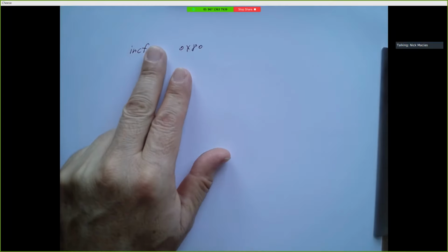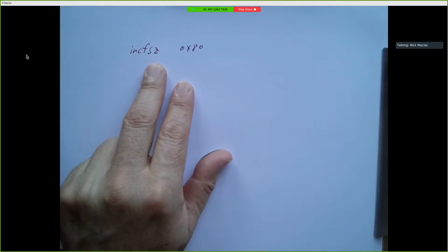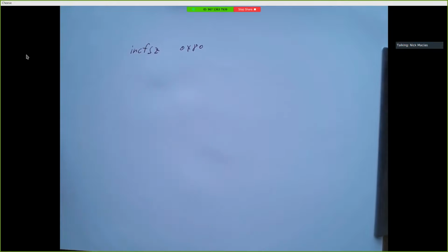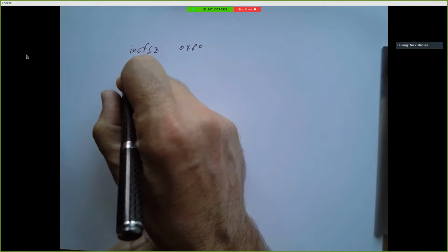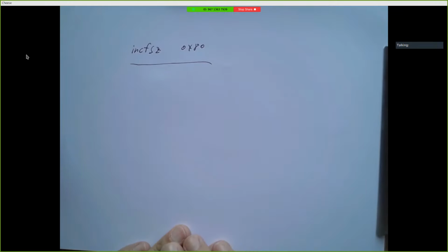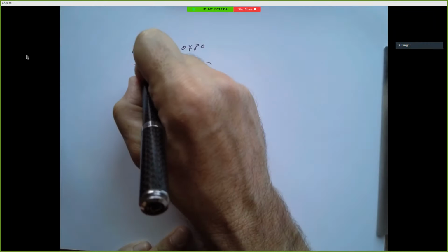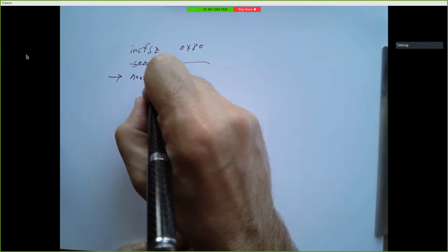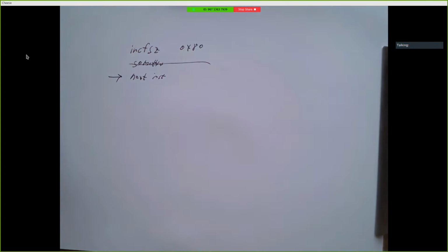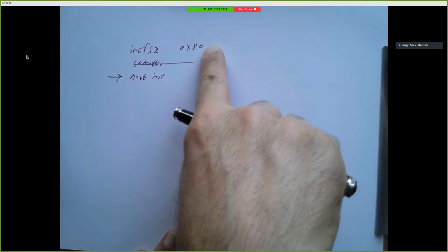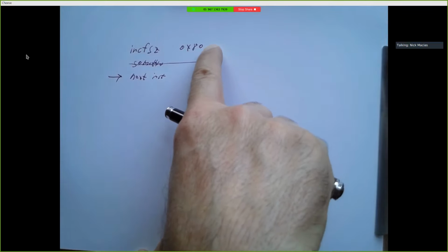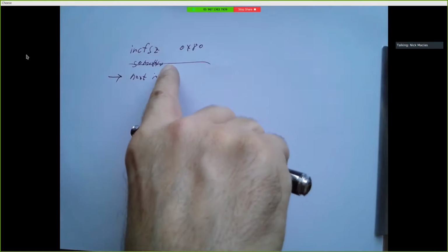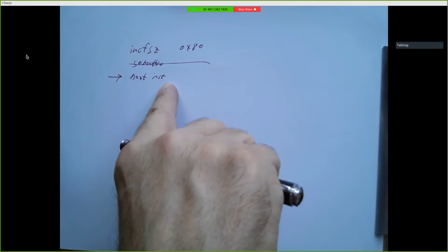So it's kind of like just an increment file register. But the SZ does one extra thing. It says, after I've incremented, let's see if the result was 0. And if it is, don't do whatever this next instruction is. Go on to the instruction after it. But if when you increment this register the result is not 0, just treat it like a plain old increment. Right? Increment that, go ahead, do the instruction after, do the instruction after that, and so on.